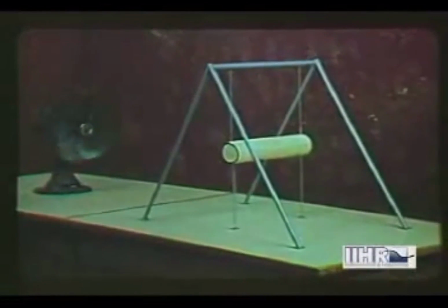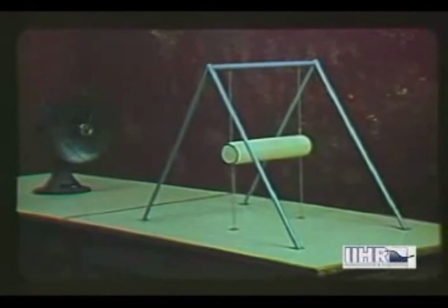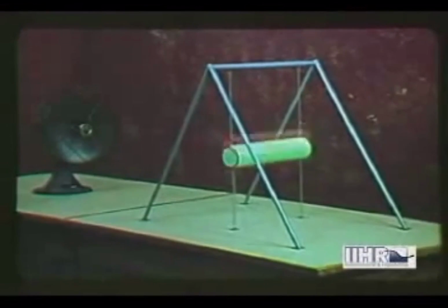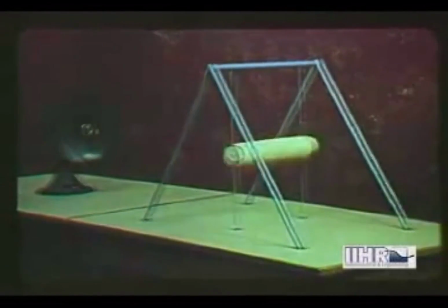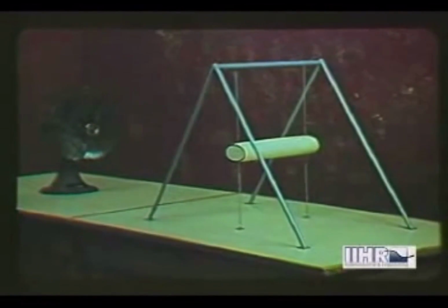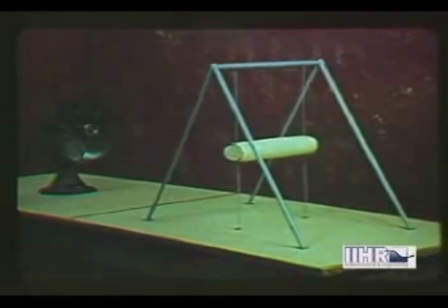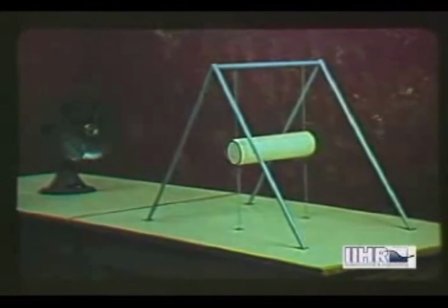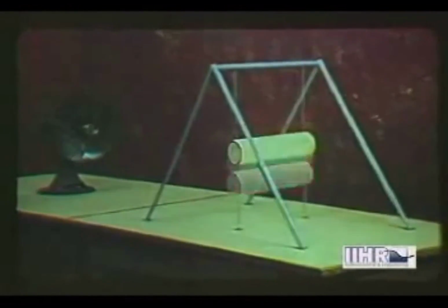If the cylinder is free to oscillate under the side thrust, as it is if suspended from light springs, it will gradually develop an oscillatory motion in the transverse direction and eventually move back and forth over a distance about equal to its diameter. An elliptical cylinder with major axis in the direction of the flow will have a more limited amplitude of oscillation, whereas one with its major axis normal to the flow will oscillate much more markedly.